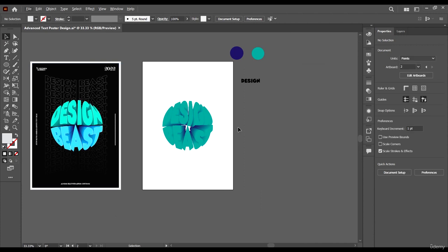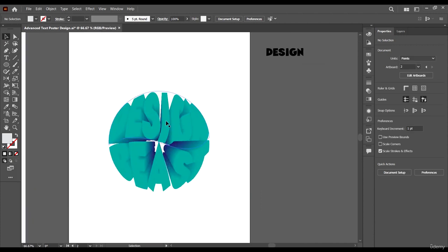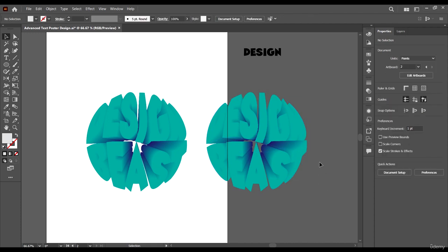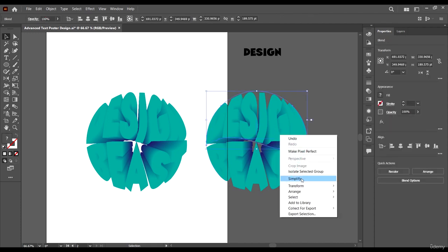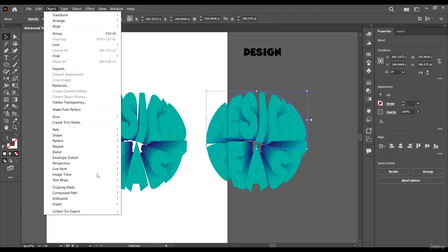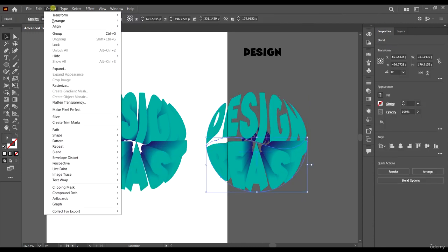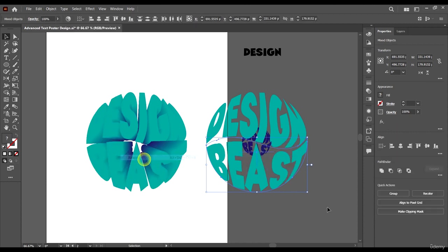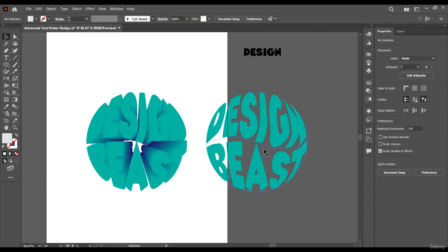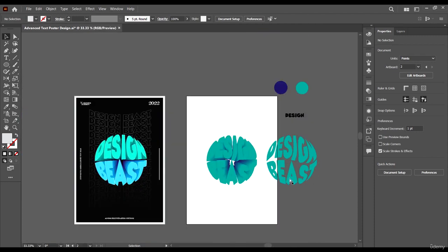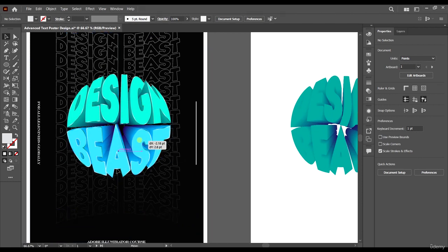Okay, it's coming alive. So the next thing will be to select the two shapes on top, hold down Alt and drag them to the right. Okay, now we want to just kind of release our blend right now. So release and objects, release. We're going to marquee select everything and deselect the ones on top and delete, so that we delete the ones under, right? And then for these ones now, what we want to do is we want to give them